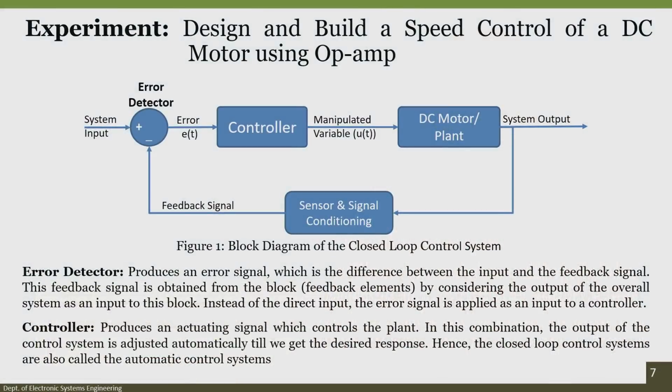We have seen interfacing the PI controller to the DC motor in order to drive the DC motor to a required set point. And we have also observed that depending upon what type of controller we are using, the gain that we have set to the controller, the offset voltages, the offset error, and the time it takes to reach the set point will always change.